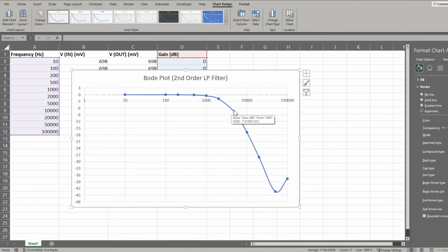Just be careful, because what comes up when you hover over it is looking at the nearest point. It's referring to that point. So ignore this little pop-up here, I'm not too bothered about that. We should be tracing from the axis to the trace, and then from the trace correspondingly up to the horizontal axis there. And that looks roughly, to my eye, about 4,000 hertz, because 1,000, 2,000, 3,000, 4,000, roughly speaking.